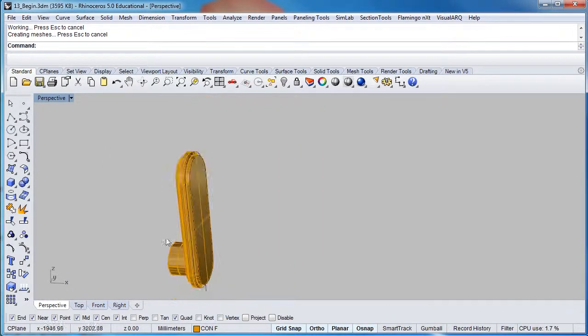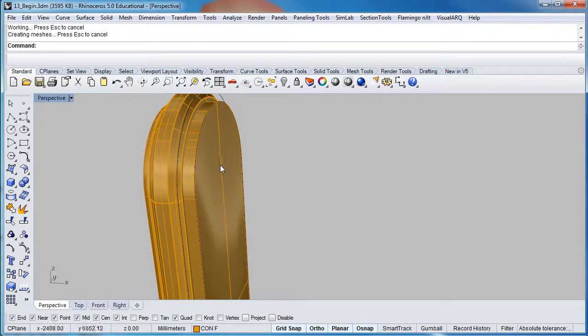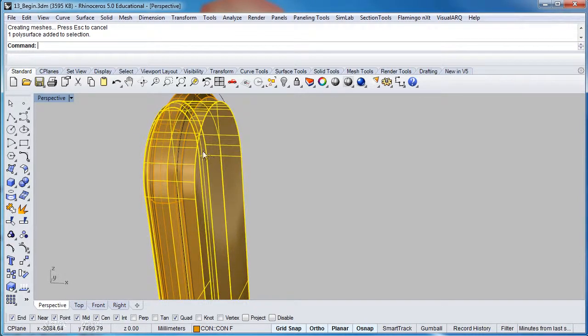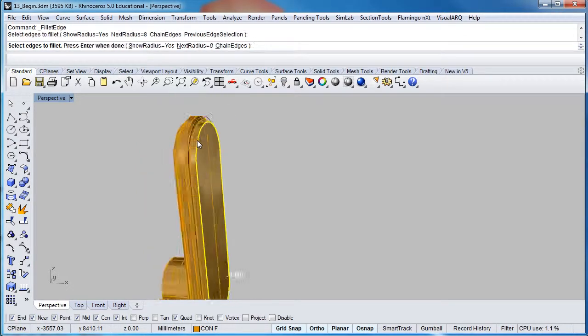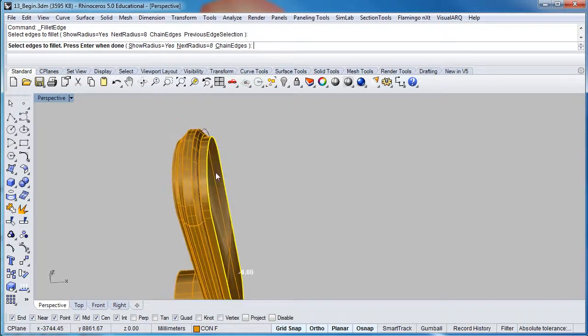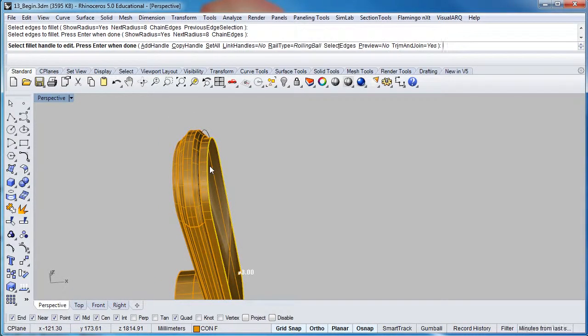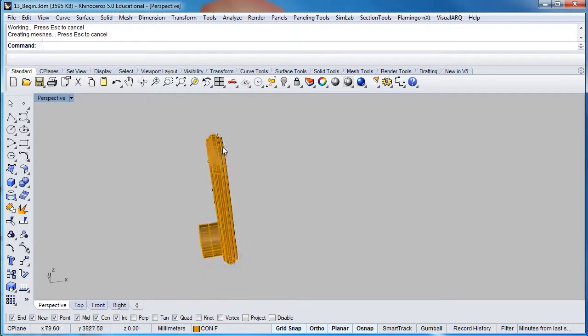Now let's repeat this process on the back face. So select the geometry, right click to bring up the command. It's asking us for the edges to be filleted on the command bar. It's telling us what size that fillet's going to be. We can just simply select that edge out, then right click and right click one more time, and it executes the command.